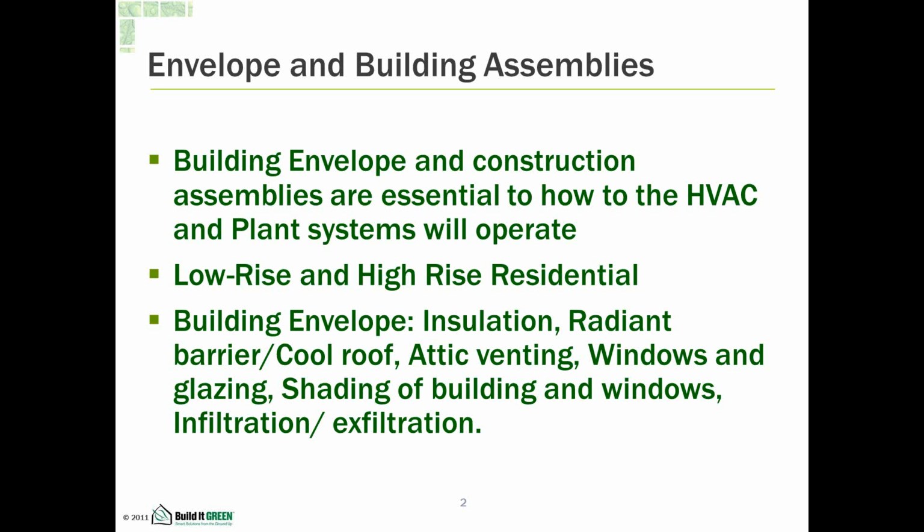We're going to be looking at low-rise and high-rise buildings together, grouping them in the same group of buildings. The main difference between low-rise and high-rise is that they fall under different energy compliance metrics. Low-rise falls under the residential energy code, and high-rise buildings, which is four stories and above, four floor levels and above, fall under the non-residential